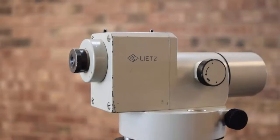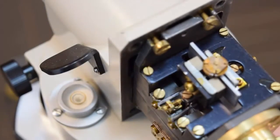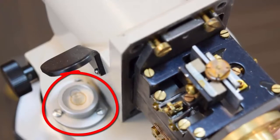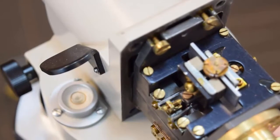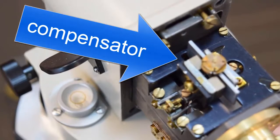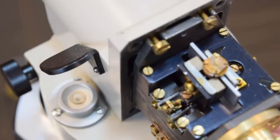Introduced in the 1950s, the automatic level contains a set of tiny mirrors that move automatically in response to Earth gravity, ensuring that the instrument line of sight is perfectly level. If the instrument settles during use, this automatic compensator simultaneously adjusts the line of sight back to the horizontal plane. Here you can see the top of the mechanism moving as the instrument is tilted. Because they contain compensators, automatic levels can give greater precision than older uncompensated instruments can.